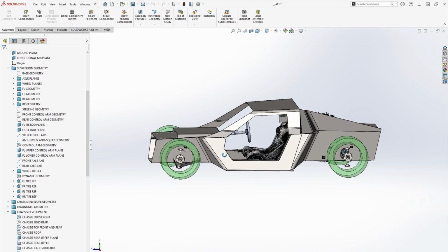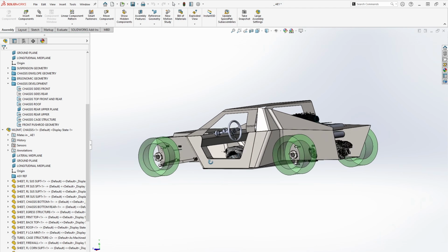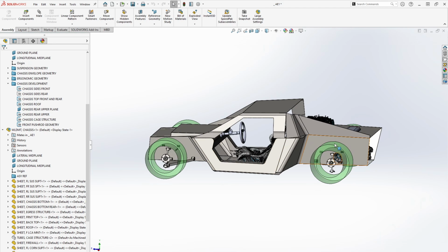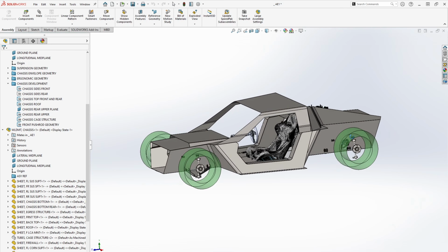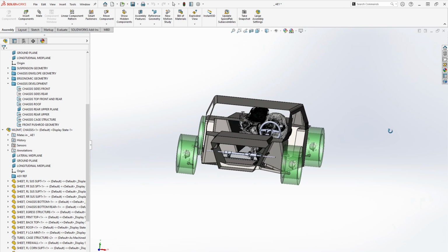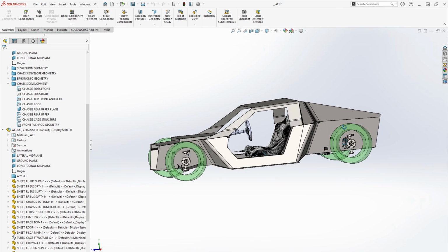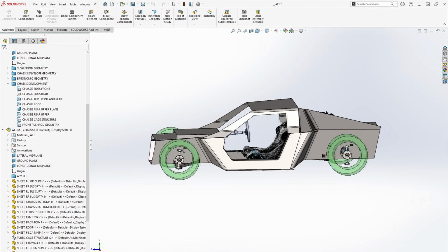So changing the wheelbase, which is the very beginning of the root file, I have changed effectively every component on the car. All the sheet metal parameters, they've stretched or grown in one way or another. That's why it took a little bit longer to rebuild, but you can see that everything has been updated just on the fly from changing 1 dimension. Really illustrating the power of reference-based design and the top-down design process.